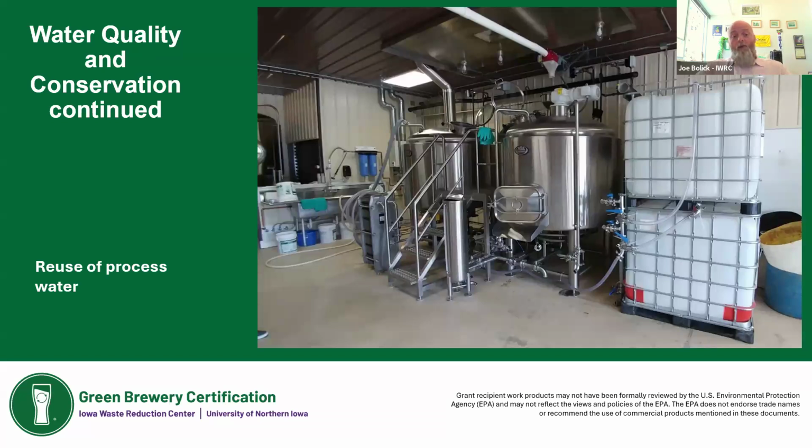What we like to see and what we recommend is any of that heat exchange water that's coming off the hot water, if you have a hot liquor tank, store it in there so you can use it for your next batch. That way, you're not having to heat that batch up nearly as long as you would if you were using tap water. When the hot liquor tank may be full, then you can reuse that water for cleaning. Cleaning and sanitation is very important with the brewing process to prevent the beers from going bad. So making sure that you have clean and sanitized equipment is vital.